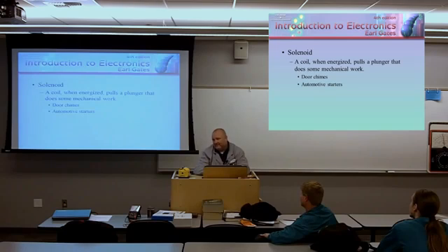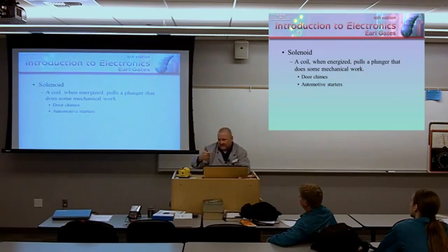So a relay has a moving armature. A solenoid has a moving plunger, a moving core, if you will. If any of you have ever played a pinball machine, the flippers are solenoids. When you hit the button, it's energizing a solenoid. That solenoid is attached physically to the flipper. That's going to move back and forth: energize, de-energize, energize, de-energize.